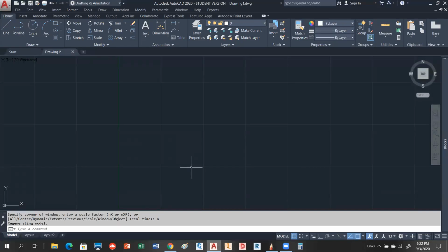So what we're going to do is draw two cases. I'm going to draw two triangles, one where we're going to close it and one where we're going to have it open. So I want to go into the polyline command. One thing about this, by the way, once you set the width up, it remembers it. So you still should have your width set, okay? So we're going to start out with a value of 2,2 and hit enter, okay? Should come on your screen somewhere.